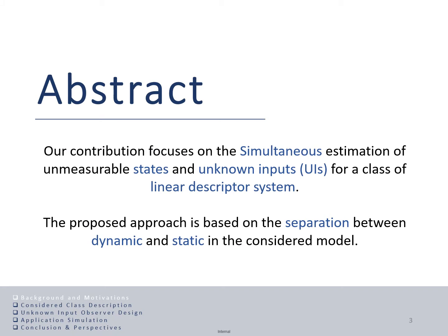Our contribution focuses on the simultaneous estimation of unmeasurable states and unknown inputs for a class of discrete time linear descriptor systems. Our approach is based on the separation between dynamic and static equations in the considered model.